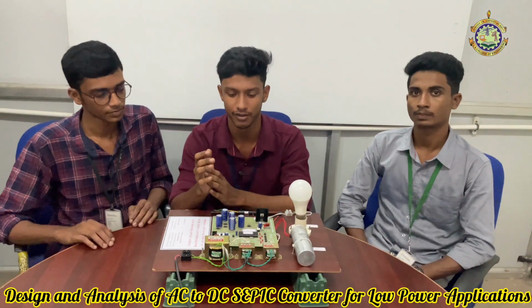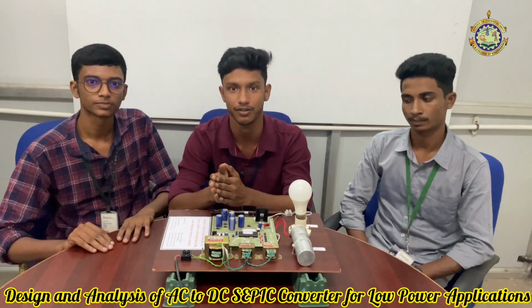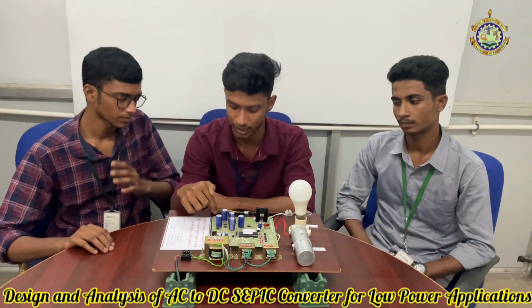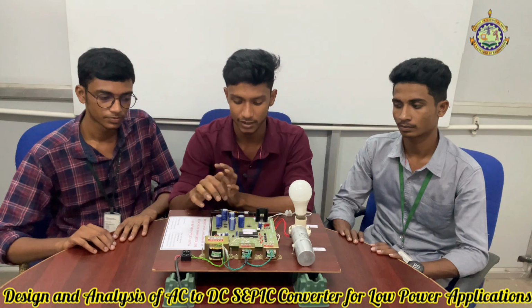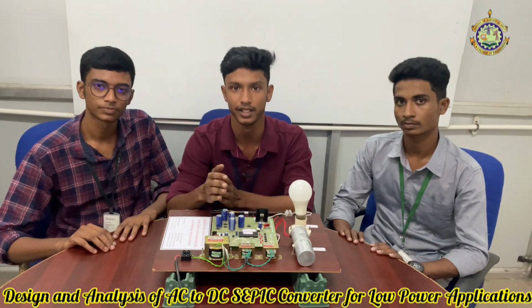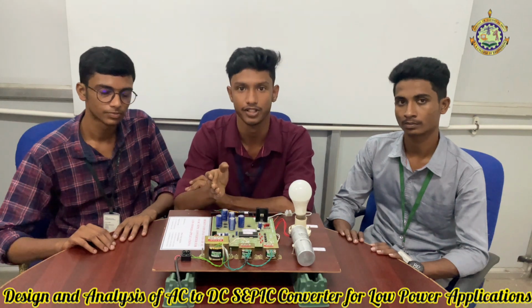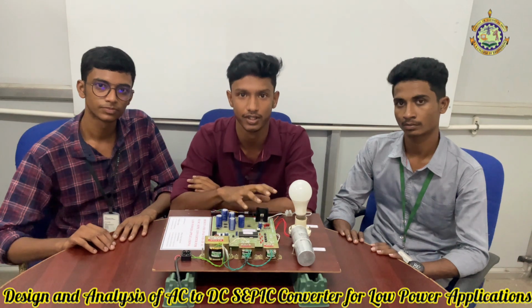Okay, let me explain the hardware components. In the hardware, we have two sections, that is AC to DC and DC to DC. The AC to DC is converted by this bridge rectifier, and these diodes are used for that conversion, and these capacitors are used for filtering of the ripple content in the input voltage source. And the second section, DC to DC, is given by this SEPIC converter topology.